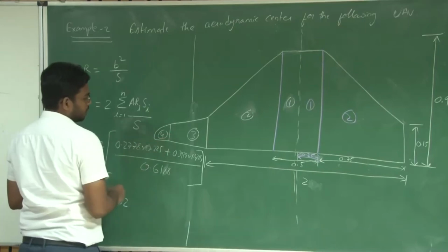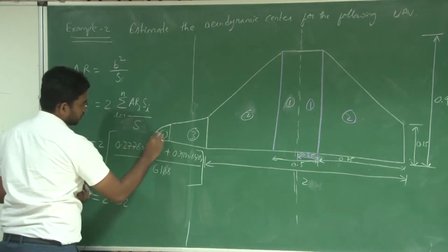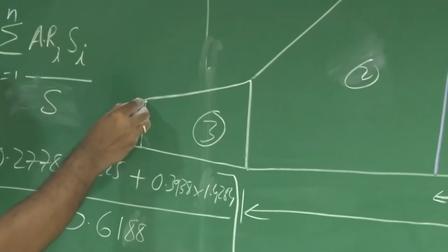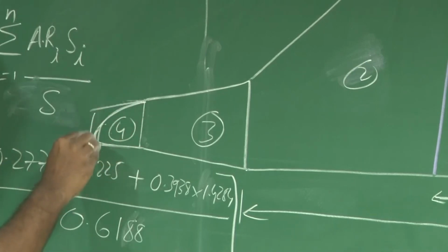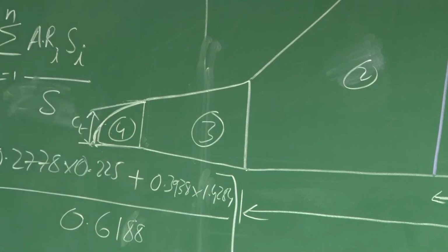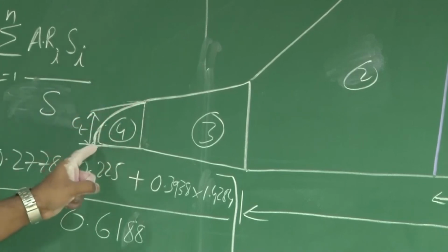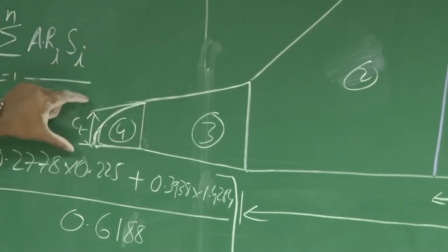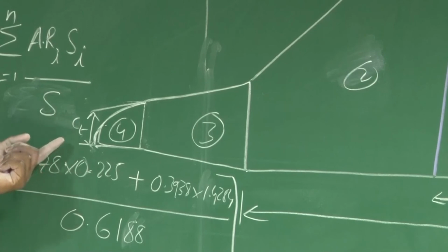Say if you have an elliptic planform like this, you will not be able to find what the tip chord is here. In that case, what you can do is extend this taper and consider this distance as your tip chord, CT, for an elliptic wing. So here the taper ends, and after that you will get an ellipse. You extend the taper of the adjacent section and find the corresponding length at the tip. This chord length will be the tip chord length for the elliptic wing.